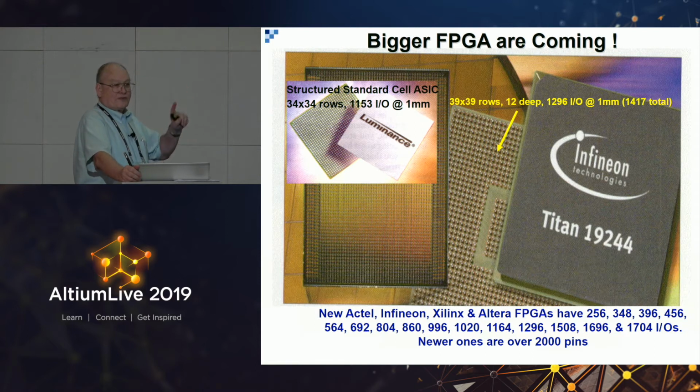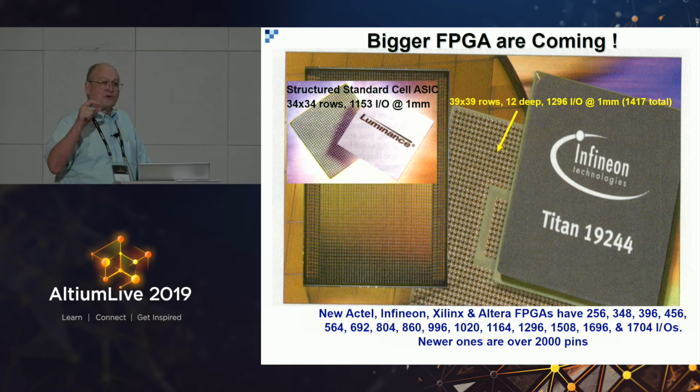At Hewlett-Packard, we developed the HDI technology in 1982, so it's been nearly 40 years for me using HDI. For the first 15 years, we treated the small microvias as just a small through-hole via in terms of our brain. That's not the right way, as you'll see throughout the day. You've got to forget a lot of what you learned about multilayer and rethink the whole layout and stack up of the PC board. Now you can use the laser drilled microvias as just another via. It doesn't hurt you. It costs you a lot of money.